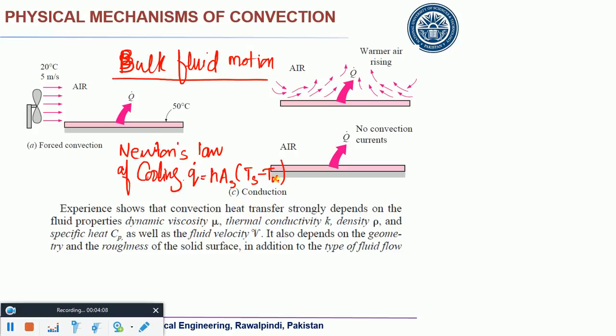So in a broader sense, you can represent the heat transfer rate in convection through this relationship. And remember, those are relationships which haven't been drawn from the fundamental principles. Now, what are the fundamental principles? Law of conservation of mass, law of conservation of momentum or energy. Those are the fundamental principles. These relationships, just like Fourier's law or Newton's law of cooling, have been drawn from experiments.